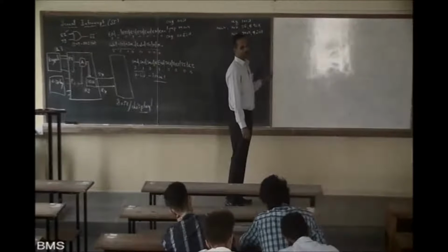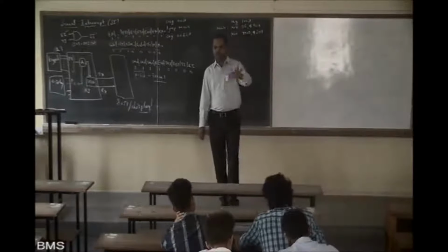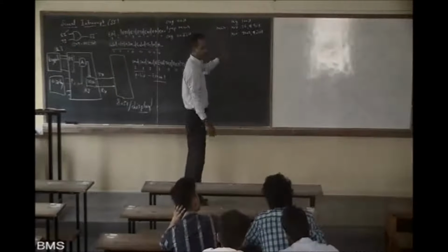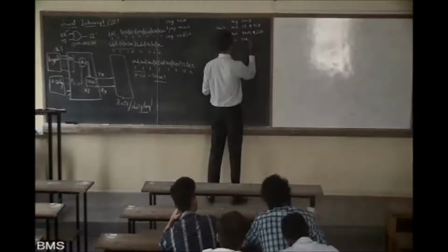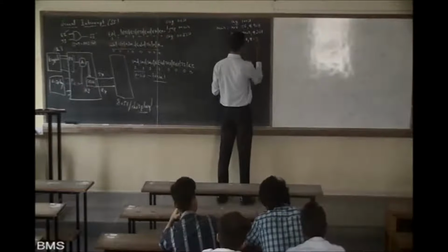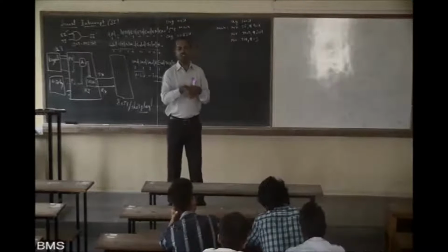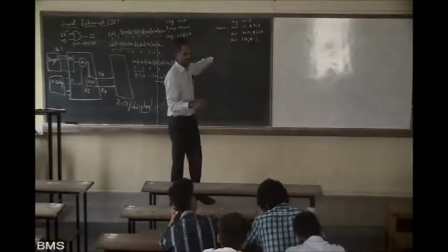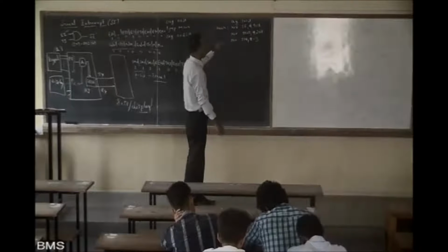Next what should I do? TMOD is in timer 1 mode 2 auto reload mode. Complete this, then we'll go to SCON. Move TH1 comma -3 or FD. It's one and the same. -3 for what? 9600 baud rate, it is FD. So it is -3. We have discussed this -3 FD concept. Next what should I do?